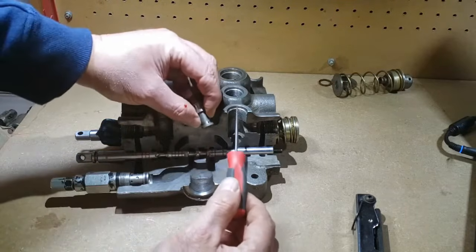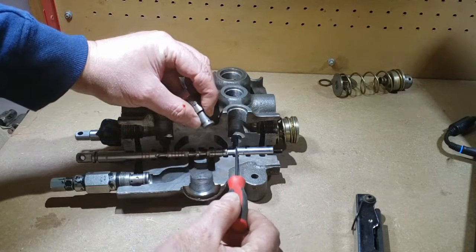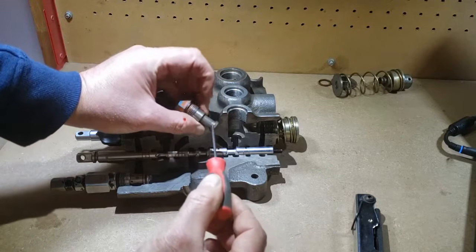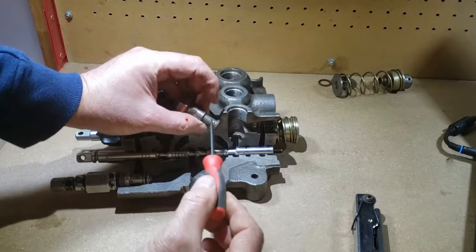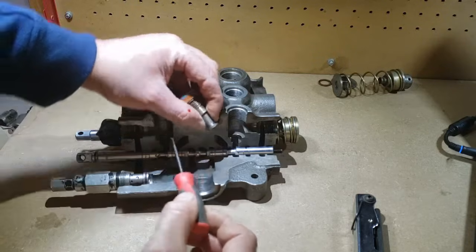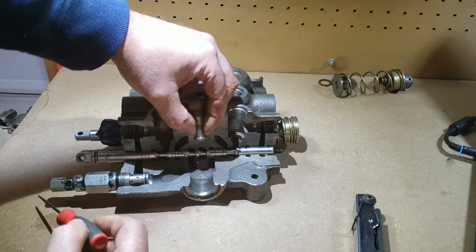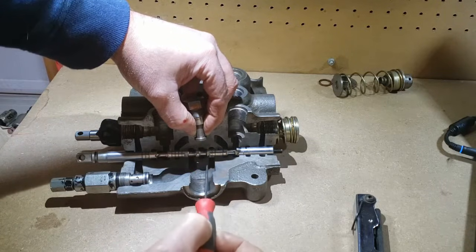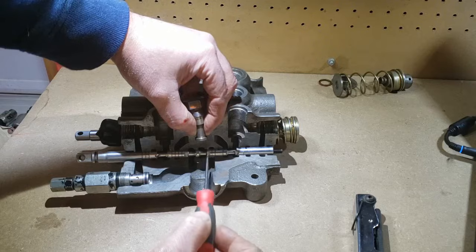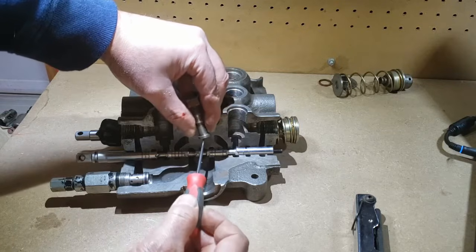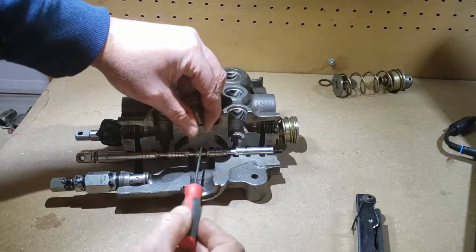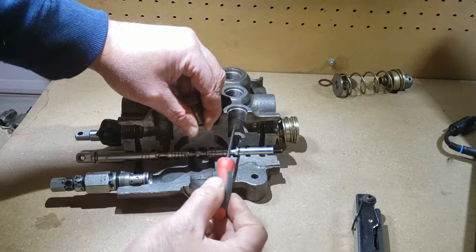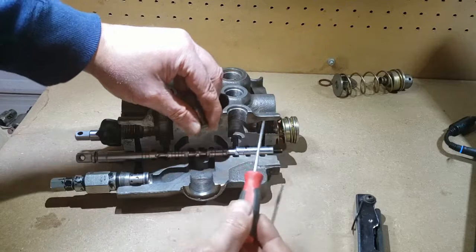What's going to happen is that 1,000 psi is going to come back here, and maybe a teaspoon is going to flow in this little hole here and get into the spring chamber and lock that load check shut. So you've got 1,000 psi holding the load check shut, and then the pump pressure is going to have to build up to 1,001 to reopen that load check and be able to flow in the intended direction into the bridge passage, across the notch, and out into the cylinder.